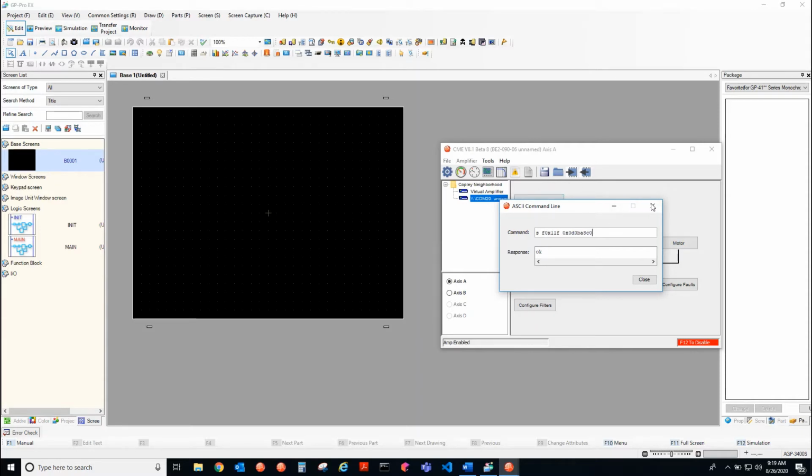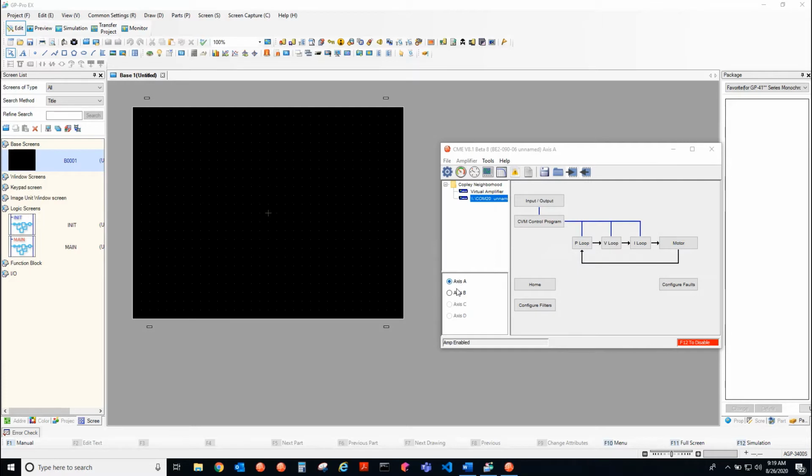Now, the IP address is not axis specific, it's drive specific. So for the whole drive, that IP address is used. You can't set the IP address to different values for different axes. However, the way you differentiate in Modbus between axes is using the unit ID. So we'll get into that. Let's close. We'll keep it open for monitoring.